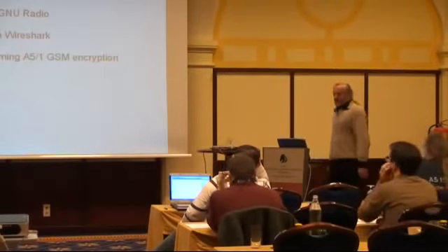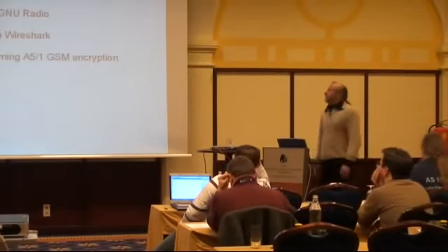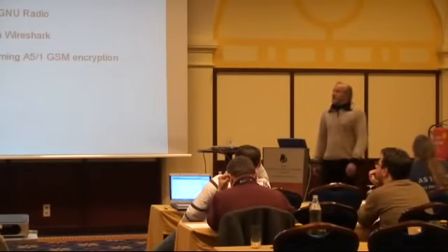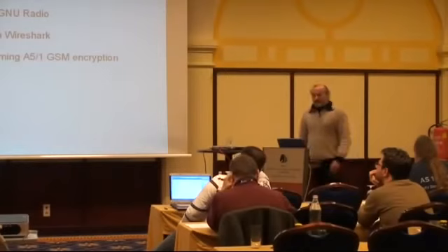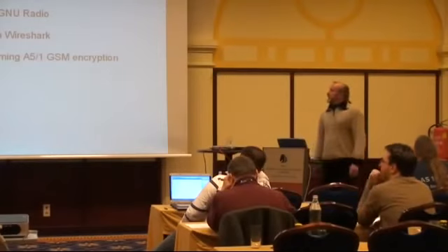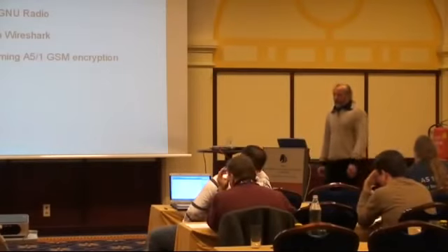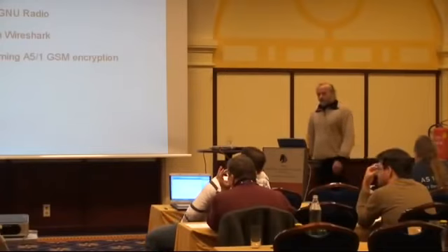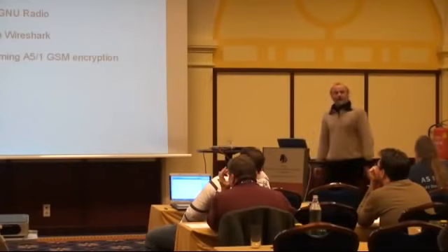The last project I want to introduce is AirProbe. AirProbe is about passively sniffing the GSM air interface. Similar to OpenBTS, it's based on the USRP and GNU Radio. One of the goals of AirProbe is to analyze the air traffic and directly feed the results into Wireshark, the open source protocol analyzer.